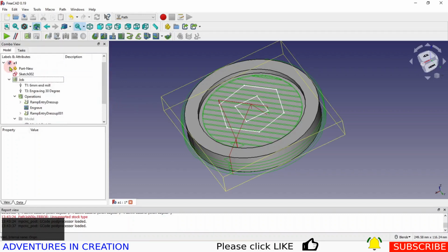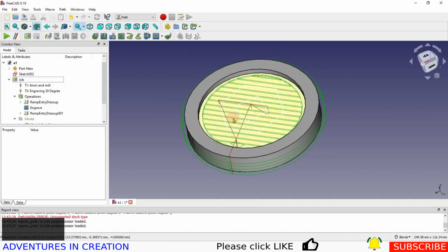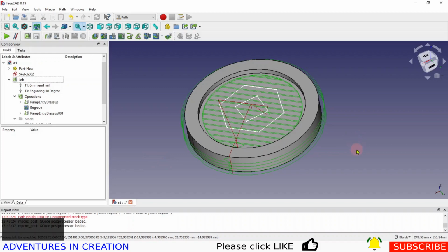All right, hopefully that's clear. Obviously your sketch could be anything you wanted to make it, anything that you decided. So if it was some kind of a picture or something else that you've done, you can certainly do that. If you're going to do text, it's a good idea to use the shape string. If you use the shape string, you can do text in it and engrave around the shape string.